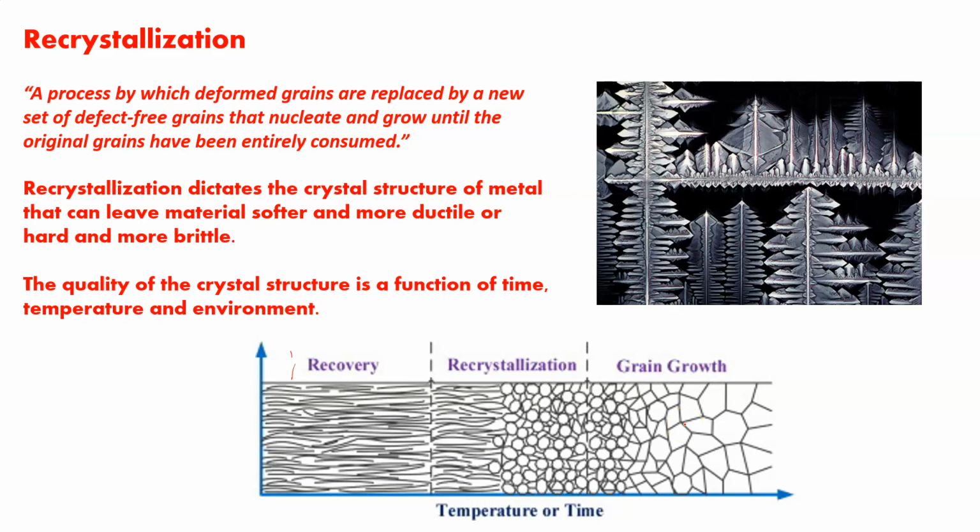So these are all things that are important to understand because they become an inherent part of the joining process, primarily because joining requires high temperatures, or usually some sort of temperature change, as well as some influences going on in the environment when you're doing welding or different types of joining applications, as well as the time that you take the material up to that state. So let's look at how, beyond recrystallization, the phase diagram plays into joining metal.